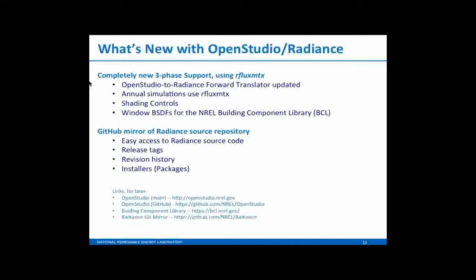You can basically say the window on the east face has a shading control on it. So something happens, that window is configurable. It can change its state. It can be clear, or it can be diffuse, or it can have a blind down, and you can define all those things. And then during the annual simulation, at every time step, that configuration can change. The distribution of that window or multiple windows can change and all contribute to a sum, an hourly sum.